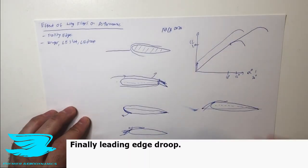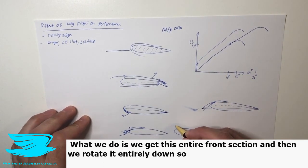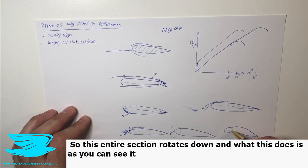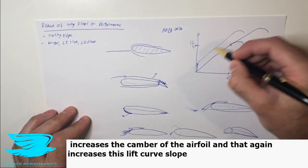Finally, leading edge droop. This is probably the most radical idea of the entire series that we've covered here. What we actually do is we get this entire front section and then we rotate it entirely down, so we get something that looks like this. So this entire section has now moved down. And what this does is, as you can see, it increases the camber of the airfoil. And that again increases this lift curve slope here.